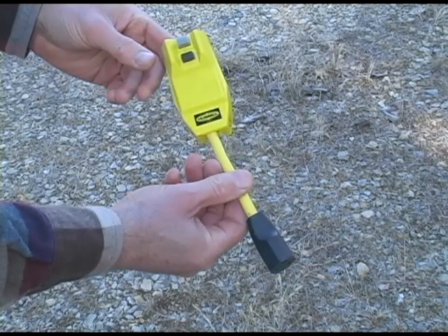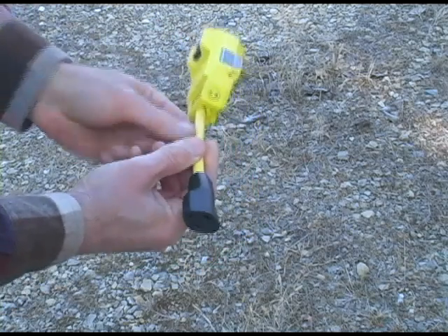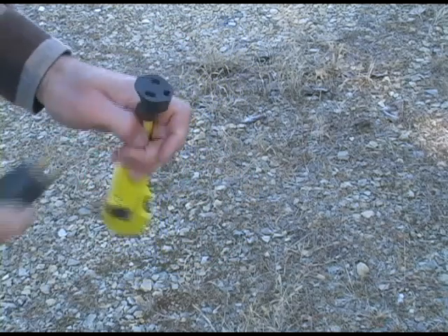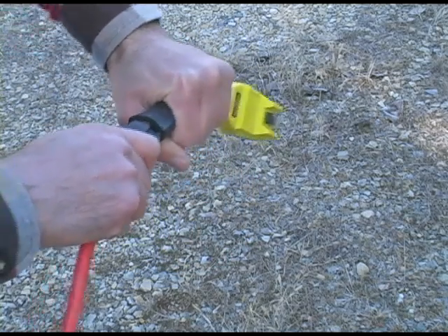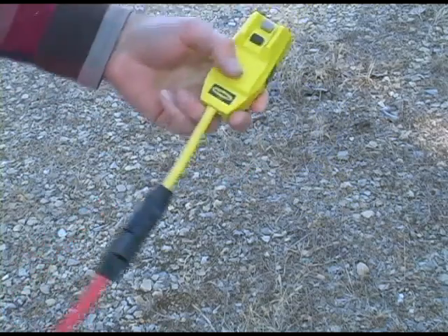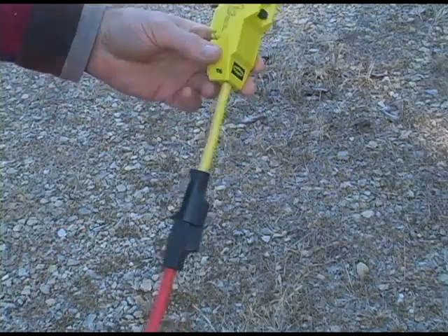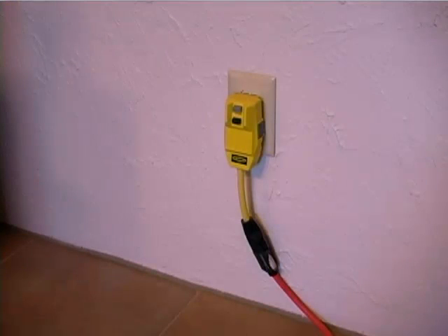For added protection against electricity, we can plug the saw into an engineering control known as a ground fault circuit interrupter, or GFCI. The GFCI monitors electric current and immediately shuts off power if anomalies suggest that an electrical shock may be happening. The GFCI's quick action greatly reduces the extent of injury when shocks do occur.